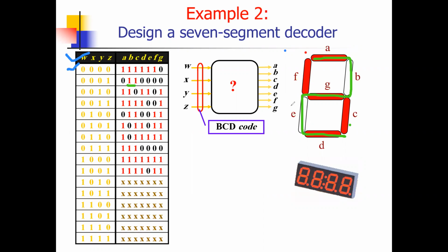If you can see in traffic signal 60 is written. So you want how many 7 segment then? 2 7 segment, because 1 7 segment will represent the digit from 0 to 9 only. BCD. If you want 2 digits, 2 7 segment. If you want 3 digits, 3 7 segments. So you have to use these 7 segments, and 7 segments are also available in the lab.